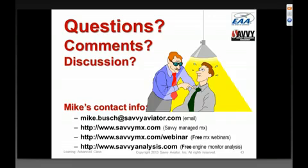Sort of interesting for those of you who fly Lycomings. Lycoming originally specified that all of their, I guess, IO360 engines be timed at 25 degrees before top dead center, which is a rather advanced ignition timing setting. And they had lots and lots of problems with high cylinder head temperatures. Lycoming is a company that has traditionally said, don't worry about high cylinder head temperatures, and they've set their CHT redline at an absurdly high value, 500 degrees Fahrenheit.